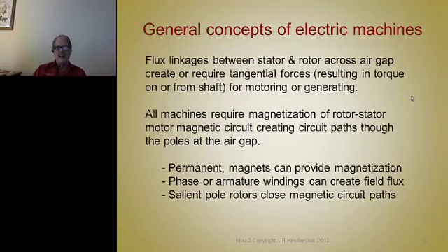The ones in your house, the motors that are used in your refrigerators and your washer and dryer and your household appliances, they're in the 1 to 2 psi air gap stress requirements. And what that is, a force is created in the air gap, times the radius of the air gap is the torque on the shaft.